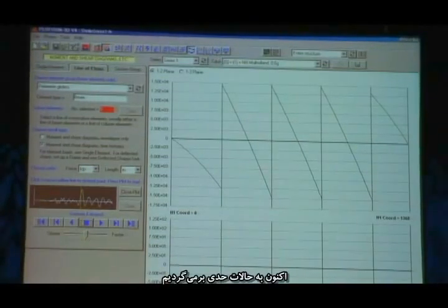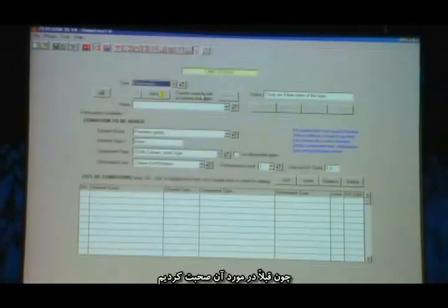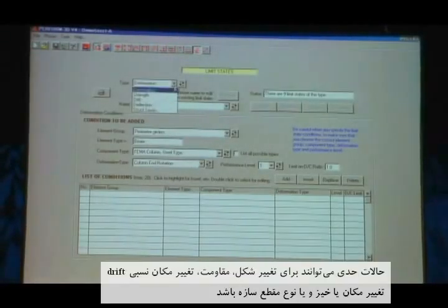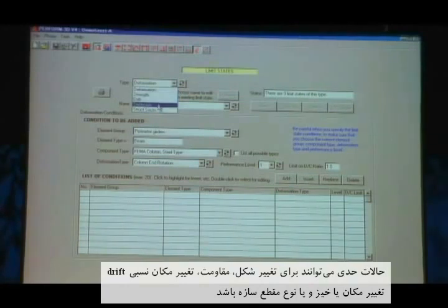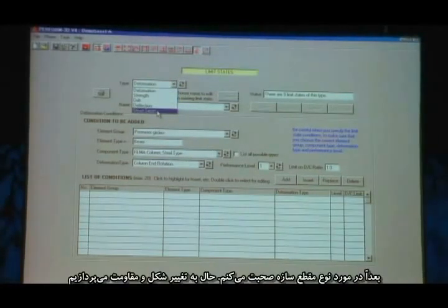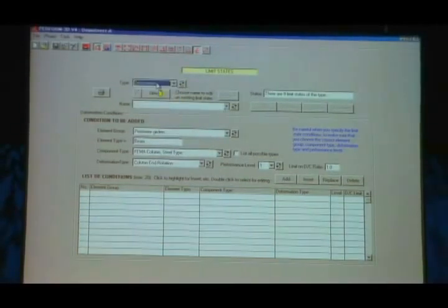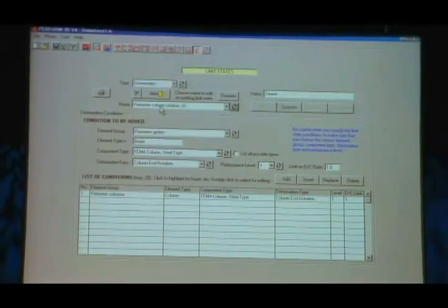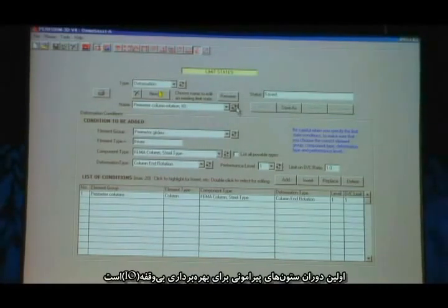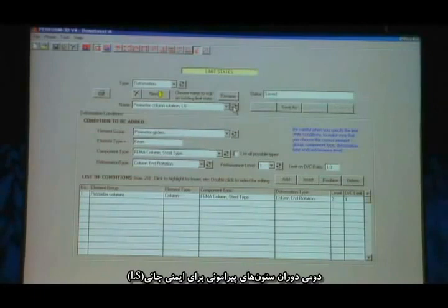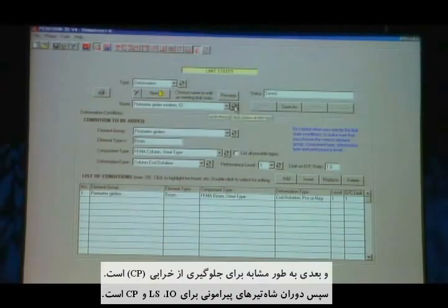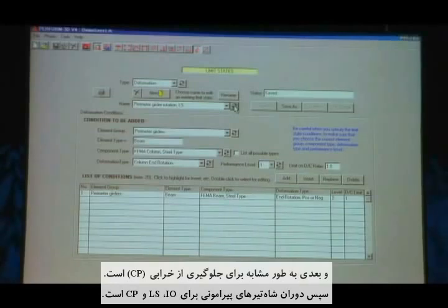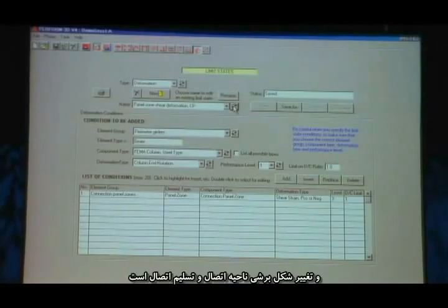Now I'm going to go back here and look at limit states, because this is what we're really talking about here. Limit states can be of deformation, strength, drift, deflection, or structure section type. I'll talk about structure section type later. Let me just do deformation and strength right now. For deformation, there are 9 deformation limit states for this simple example. That's not very many. First one is perimeter column rotation for immediate occupancy. Second, perimeter column rotation life safety. Same thing, collapse prevention. Then the perimeter girder hinge rotation, IO, LS, and CP. And panel zone shear deformation, the panel zone yield.